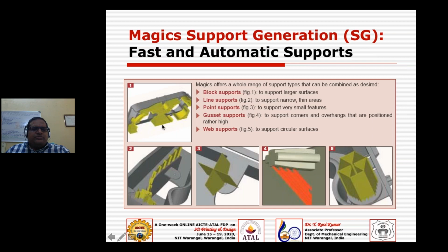Of course you have some support structure. We'll come to design for additive manufacturing slowly. In that, supports are the main criteria, where you can combine the model and support. Instead of giving the same pattern to the model and support, the support is just for giving support, like a scaffold. It is given for ease of fabrication, to give some strength to the model temporarily without falling. You are going to remove it once it is printed.